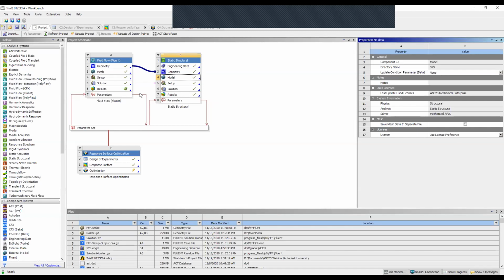In your case, if you 3D scan something, or if you did a topology optimization and you got an STL file, you're going to have to do some work and create your own geometry based off of that STL file. Of course, you could take the STL file and convert it over to solid, but because that's going to have a lot of surfacing on that geometry, we're not going to be able to grab a feature and apply a parameter to it, because a parameter does depend on a feature. So I hope that answers your question there.